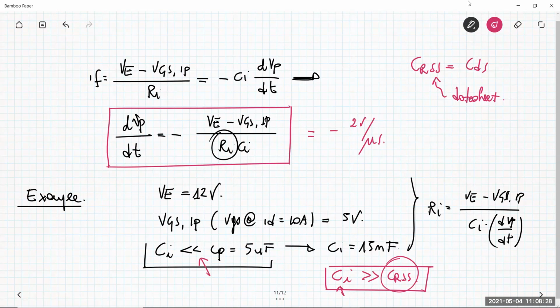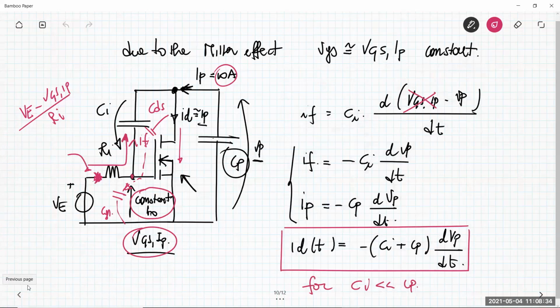Another consideration that we have to make about this circuit is about the MOSFET. The MOSFET has some static considerations: the current higher than 10 amp, the voltage higher than 200 volt. But another consideration is the dynamic characteristic of the MOSFET, because the MOSFET has to be turned on in a time interval that should be much lower than 30 microseconds.